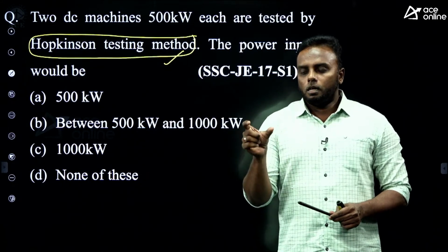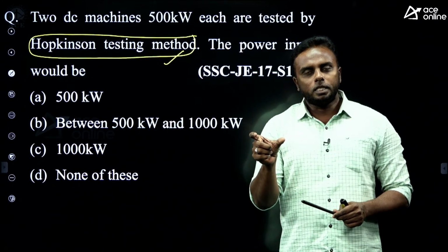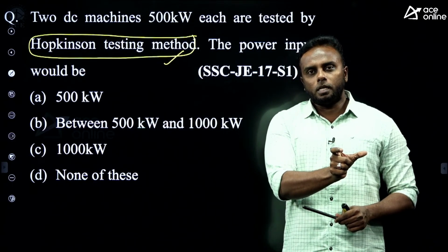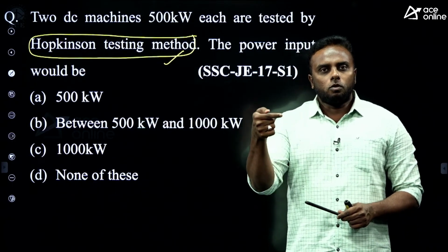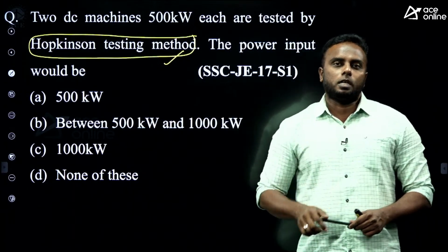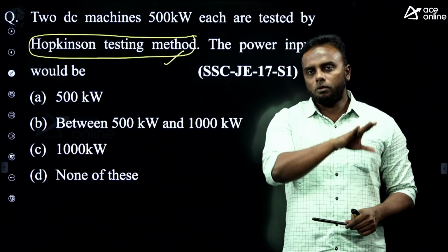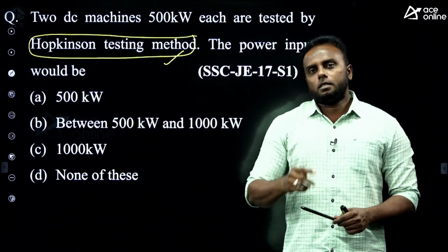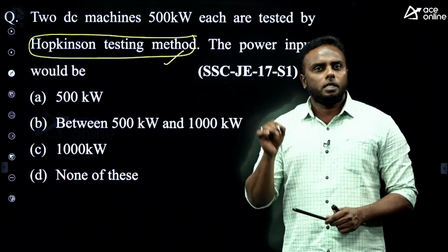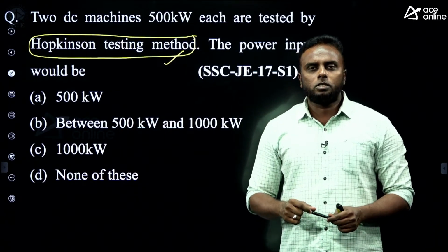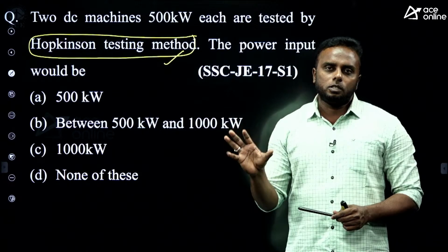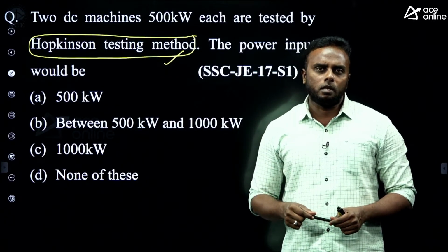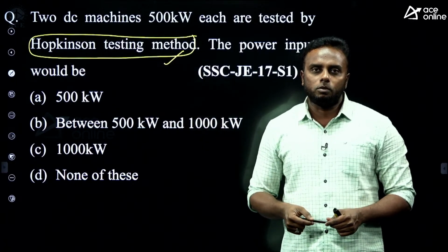Regenerative, because suppose a motor is there. What is the input of the motor? Electrical. And a generator is there. What is the input of the generator? Mechanical input. So the motor will supply mechanical input to the generator, and the generator will give whatever electrical power is developed back to the motor. So they will exchange their powers. But it will take a small power only, just to meet the losses in these 2 machines. Very small losses will be there, generally not beyond the capacities of the machines.